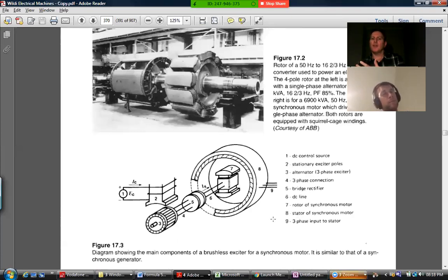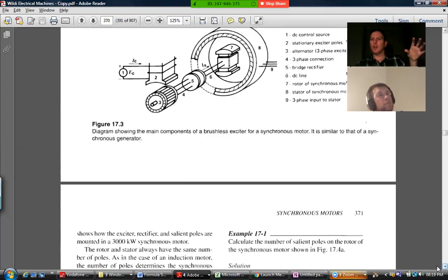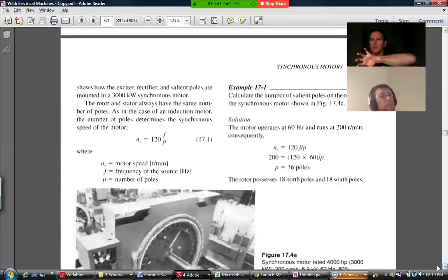But even if you did that, you'd still be taking current from the grid, from the line, to help you. So you do have to subtract it off when you're working out your efficiency. But it won't be seen as a torque on the shaft, whereas this one here would be seen as a torque on the shaft. It would have to cause extra line current to flow in here to generate that extra torque. So it's a little bit of a difference whether you visualize it as a generator inside there or as current coming in straight from the line.